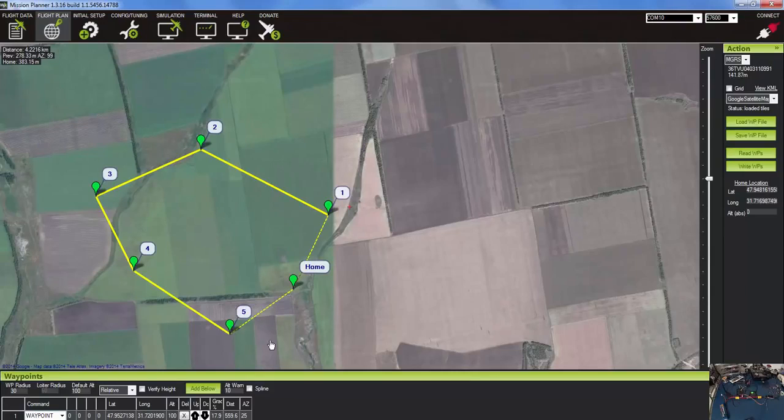The other thing we're going to need to do is go here and change the radius. Mine is set to 30 meters. I find this a good value. I have also read on the internet it's a good value for airplanes, FPV planes. If you have a copter like multi-rotors, you set the loiter radius and the altitude. This is the altitude you'd like the airplane to fly at. I've set mine to 100. You can change it to 80 meters or whatever. There's something you need to know about this, and I'm going to talk about that later.